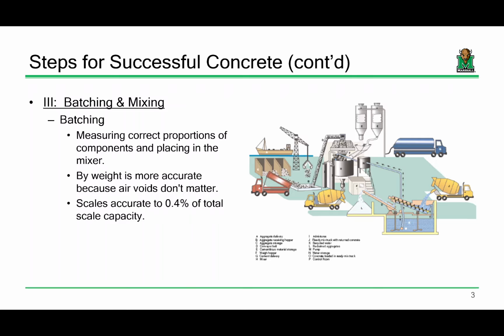We didn't say you need 2 cubic feet of cement, and 6 cubic feet of sand, and 21 cubic feet of gravel, or something like that. It was just the weights. Weights are far less ambiguous than volumes. Even though we use sort of a volumetric approach for the math, at the end of the day, the weights are what's accurate.